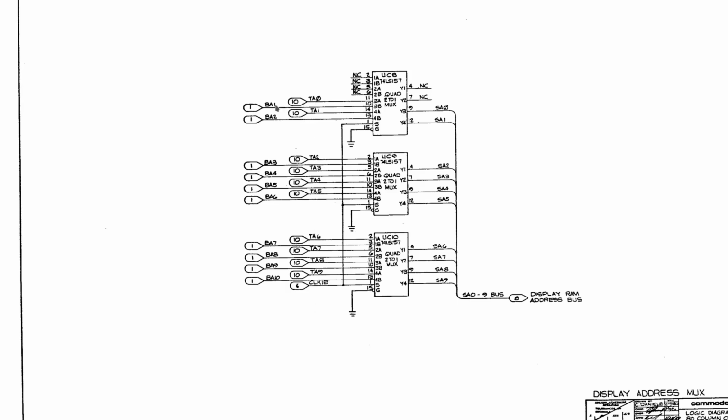And you can see here there is a slight offset. The video chip has address line 0 on this input 3, while the CPU has address line 1 on input 3, and those are switched against each other. The reason for that is the video chip counts this address, but it reads both bytes, as we've discussed, for the even and the odd addresses, while the CPU has basically 2 different addresses, and it's using BA0 in some other place, we'll see in a moment, to select between the odd and the even RAM chip. So that's why those addresses are shifted here. And that's for the 80 column model.